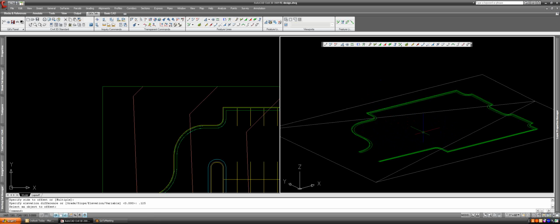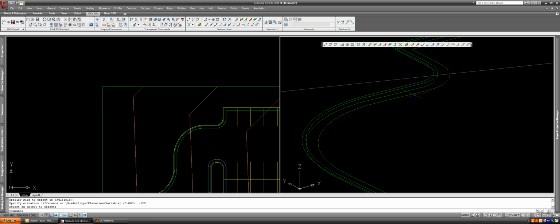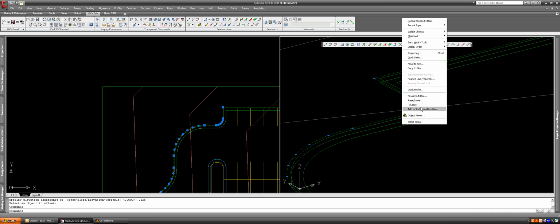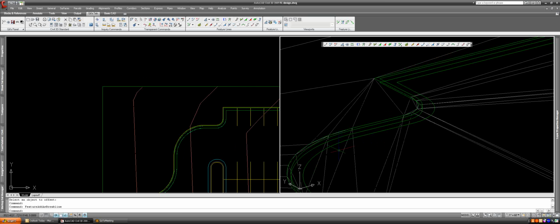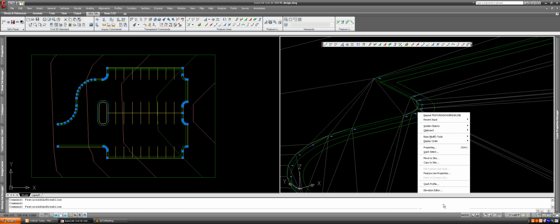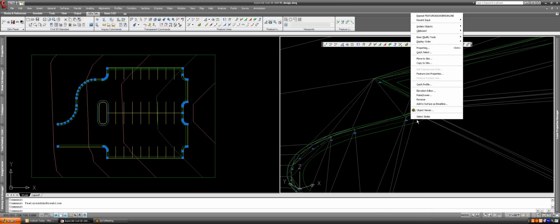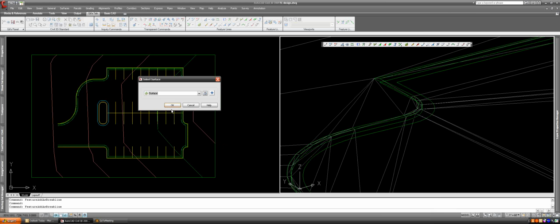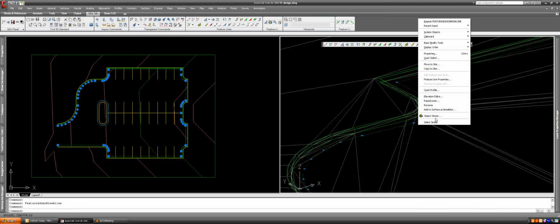Okay, if I add these particular feature lines to the temporary surface that we have now, you'll see and picture exactly why we did that. Even though we're going to delete the temporary surface, at least this will give you a good glimpse of what we're doing. Add it to that surface, click OK. And you'll see the surface change here. Select here, add. All right, bottom. Now you'll see a big change here. And one more.